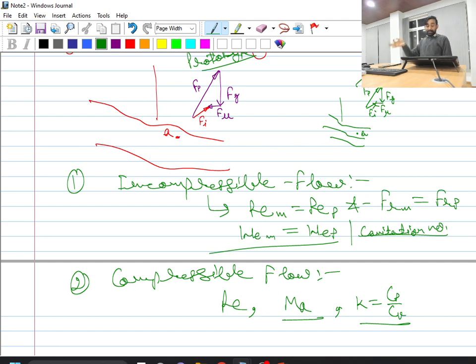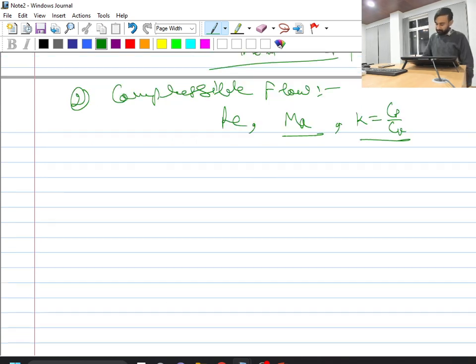Okay, but you will find that in the majority of cases geometric and kinematic similarity are easy to satisfy, but from a practical point of view you cannot always satisfy dynamic similarity. That is one very important issue between model and prototype, and to avoid it we have to go for some sort of extrapolation of the data. How? I will show you with the help of one example.